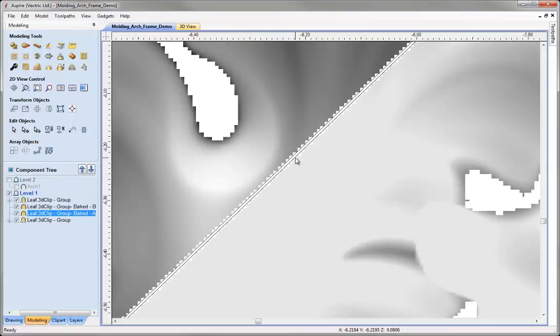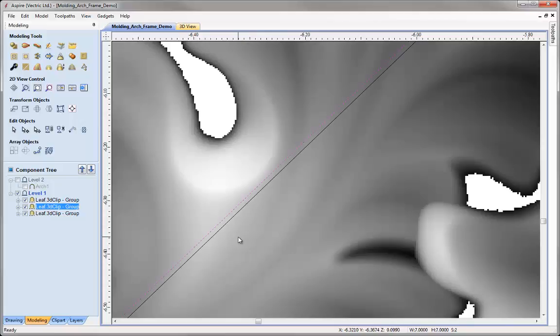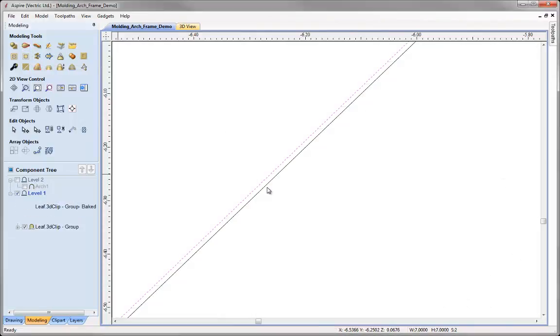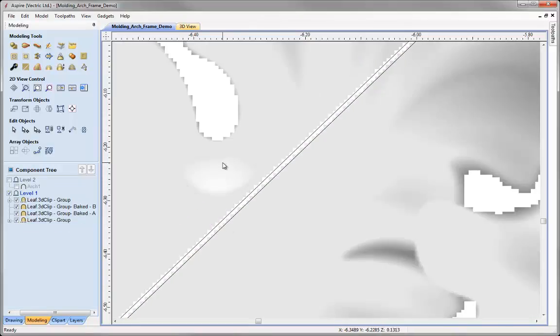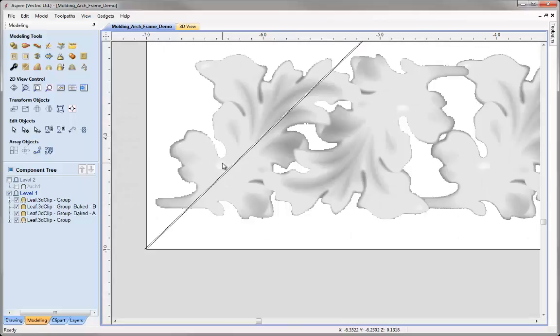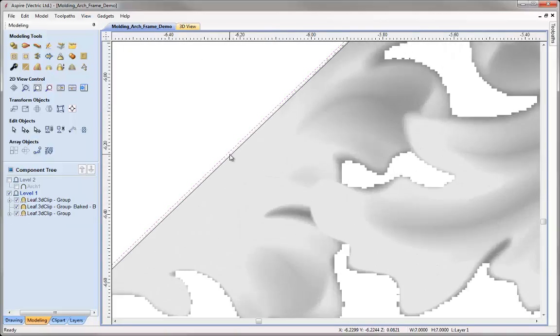And in actual fact I've lost a little bit of the part on this side of the line here. So I'm just going to hit Control Z straight away, take my line there and just move that out even a little bit further. And then I'm going to reselect the component, reselect the line, go back to the split command, and now I can see I've got that overlap of pixels I'm looking for. So if we zoom out and take a look, I can delete this piece here. I should be able to delete my second line there.